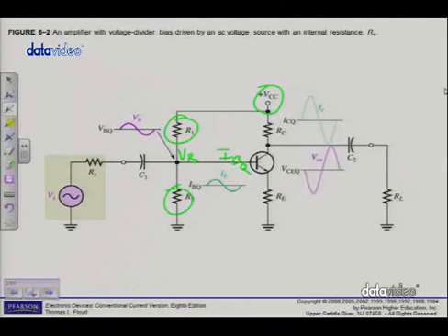Alright, once I've biased, I've seen that it is a DC operation, DC voltages. Once I've biased, then I can apply the signal that I want to amplify. There's my small signal that I'm amplifying, and I can see on the output I have an amplified signal, only it's 180 degrees out of phase, which we'll also discuss just now.